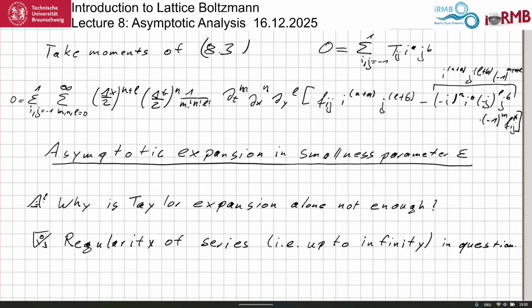Even if you don't refine the grid, you just do this simulation with these oscillations, and then you apply a low pass filter. If the low pass filter is strong enough, it will dampen out this noise, which is much stronger than the actual solution, and out comes, only through post-processing, the correct solution. So the correct solution is somehow hidden behind the oscillations.